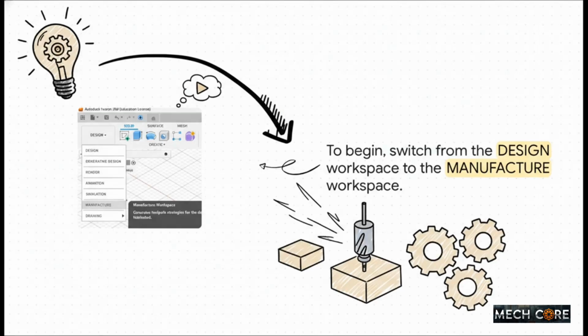And the best part? Getting started is actually super simple. Your entire journey from designer to maker literally begins with a single click. Inside Fusion 360, you just go up to the top left, switch your workspace from design over to manufacture, and boom, a whole new world of tools just opens up.